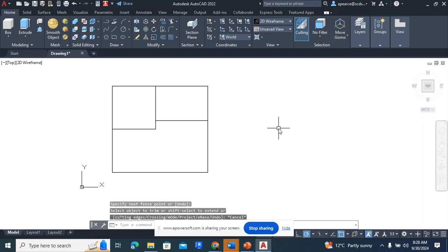Amir. So, did you choose draw a line? Well, you got the 3D on okay. So here's our line, right? When we click here, yours is just zoomed way out. Type in 55, and then 50, 55. Type C and enter. That closes it. How sweet is that, eh?